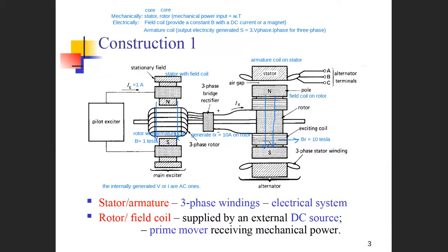As the rotors rotate, the stator coils, or armature coils, cut the magnetic field produced by the rotors. If the rotor has a constant rotating speed, this makes a rotating cutting, which generates a rotating magnetic field, which generates the AC voltage on the stators.